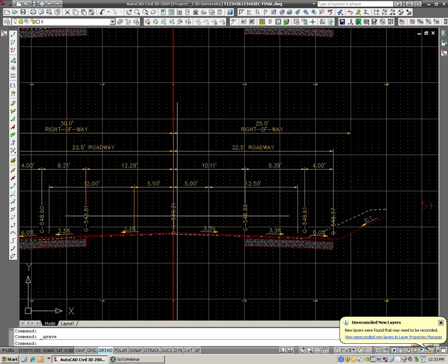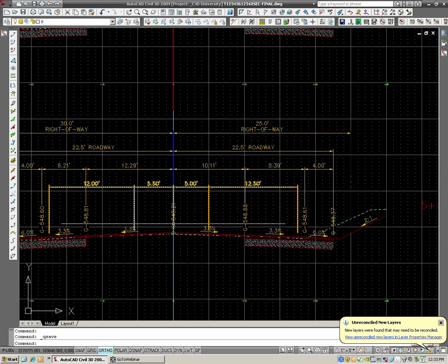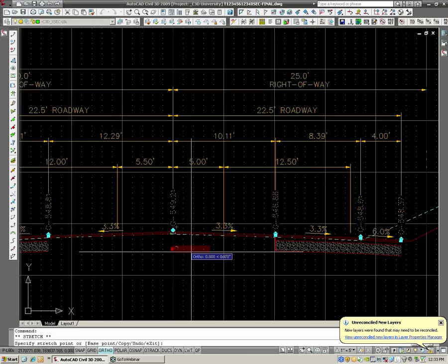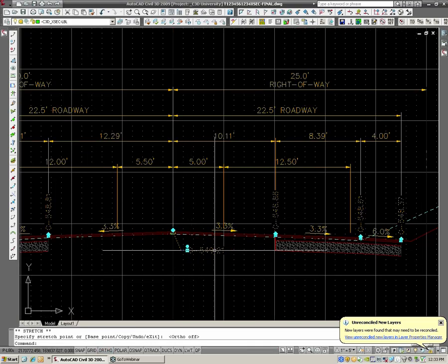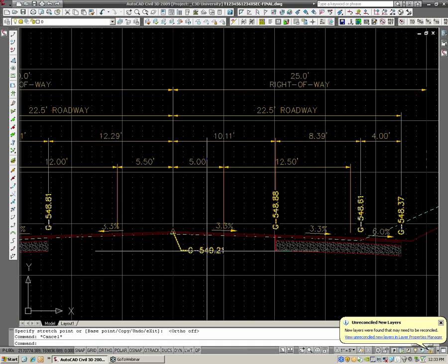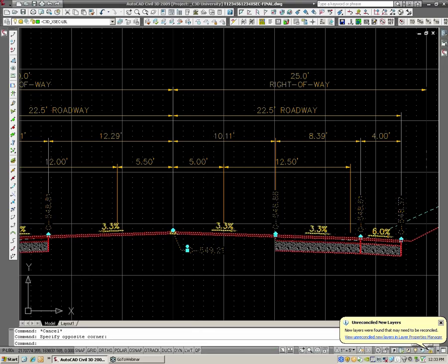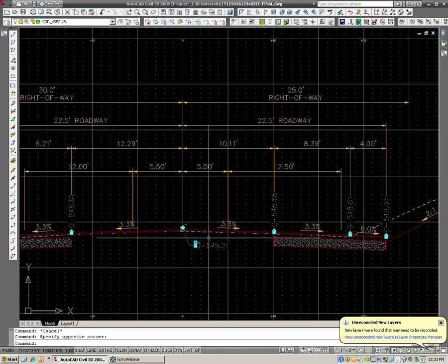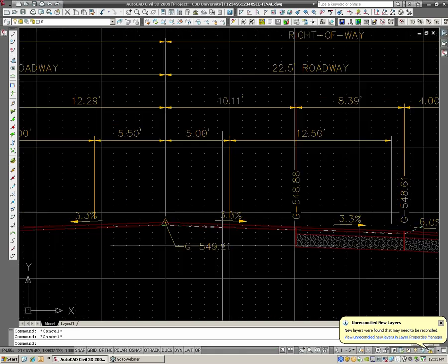Like I said, in here you can move these spot elevations down if you don't want the G. I understand the G for there, but say you don't want the G when you slide it down and you want to get rid of this G. You click on it and you think, oh, well, I can't edit it. Or say I want to add some text after this. What you need to do is hold down Control on your keyboard.